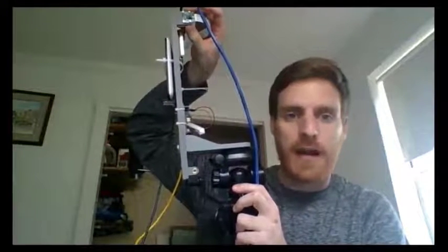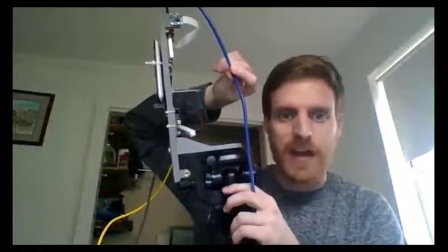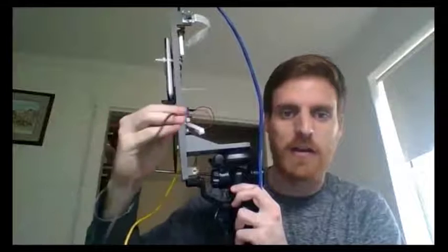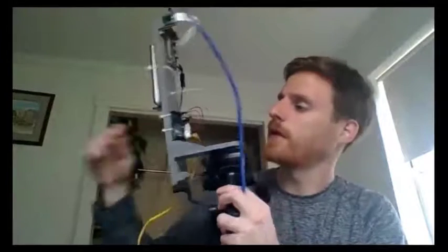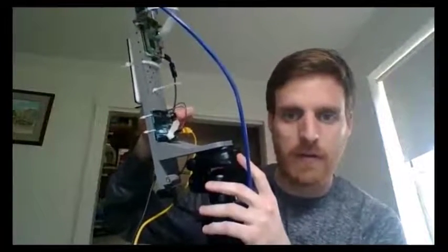The light then scatters off the object and some returns back to the LiDAR itself. This light is then detected by the receiver or Raspberry Pi camera, which is mounted here at the top of the LiDAR mount, which acts as our data acquisition, analysis, and interpretation hardware. The Pi is connected to a laptop through a Cat5 cable right here, and controlled using VNC software. There's also a power cord, which is located right here, which is connected to a mobile power source. Right here, we have an Arduino, which is providing power to our red line laser.